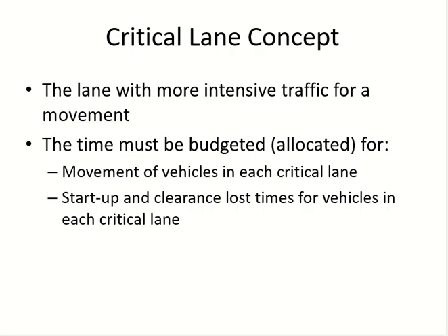But for example, if I have 2 lanes, by chance, both of them have the same number of vehicles. Just by chance. I have one lane for straight, one for left turning, and both volumes in the peak hours are equal. Then what? Which one is the critical lane? Volumes are equal.